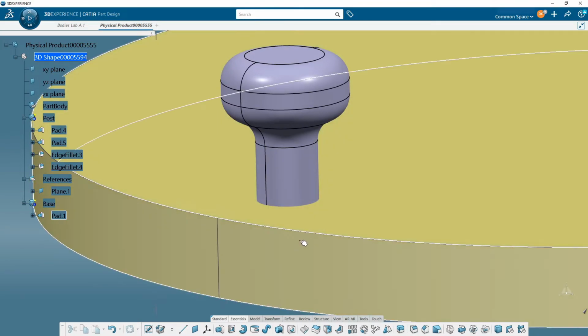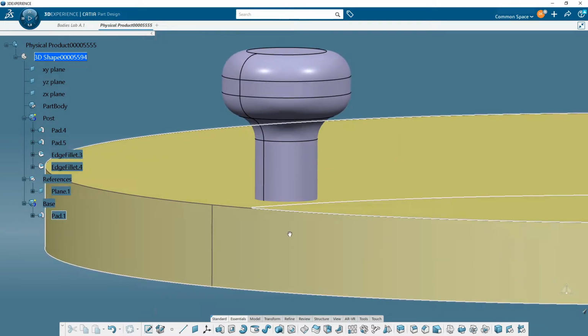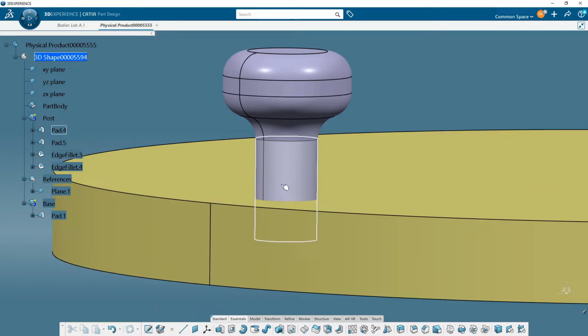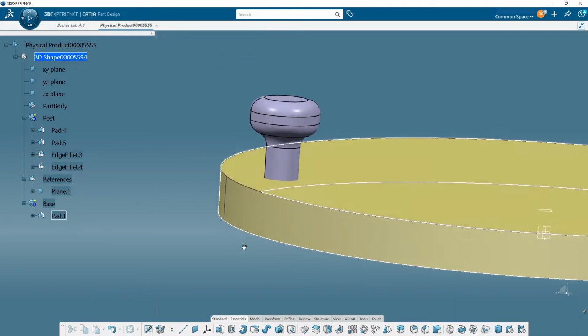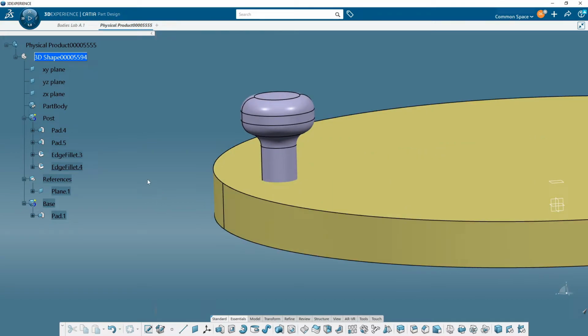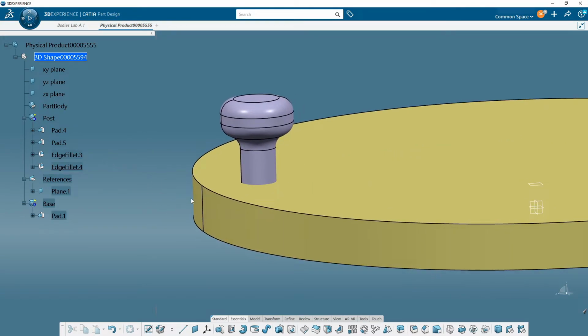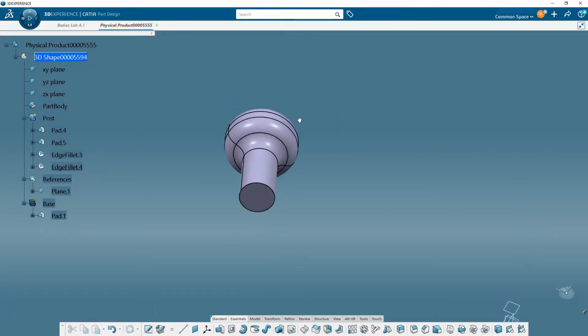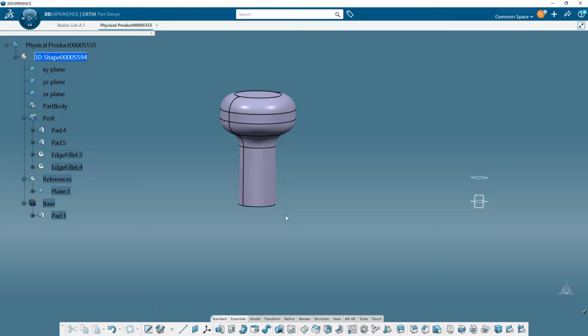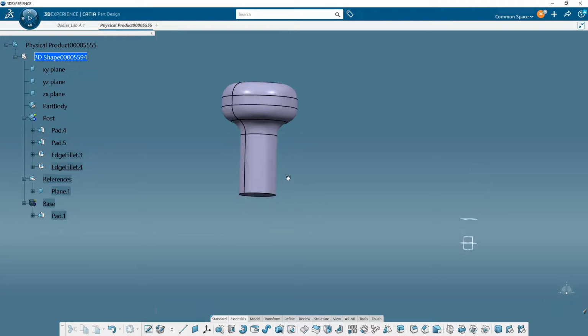So you kind of have to do a couple tricks here to get this to work out, but ultimately remember that this is just an exercise to show why we use the Boolean operations. And actually tricks are a valid thing. So I'm going to take this base, I'm going to hide it temporarily so I can see this. What I need to do to put a nice fillet on here that wraps up here, I need to have some kind of an edge or a corner to put a fillet on, just like I did when it was connected to the yellow part.